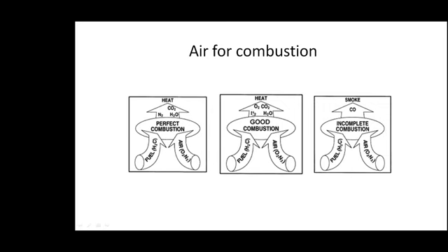So what is that O2 level? That has to be done through trial and error. In the case of a liquid fuel fired boiler, like furnace oil or even diesel, it will be around 3 to 4%. In the case of natural gas also, it will be around the same, 3 to 4% oxygen means good combustion. In the case of solid fuel fired boilers, it can go up to maybe 6 to 7%, depending on the type of firing equipment that we are using. That means solid fuels require more excess air compared to gaseous or liquid fuels.